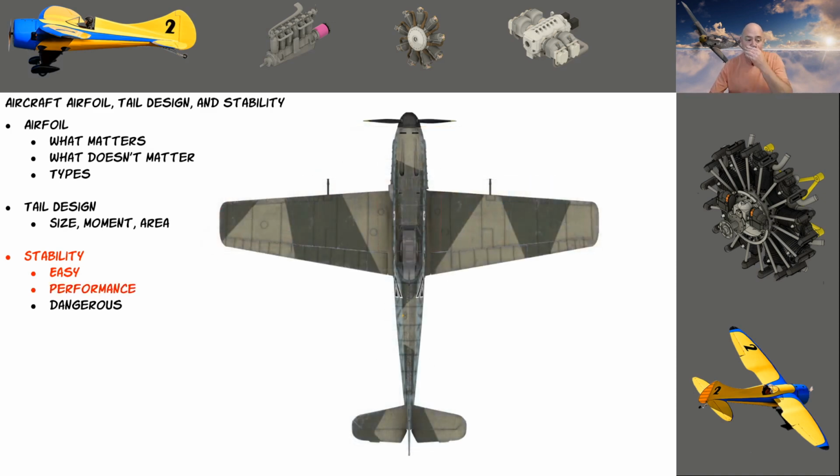So then we start talking about a plane that is easy as far as stability, but it is higher performance. So you might have a fully symmetrical wing. It might be a go-fast plane. And if you don't know this, an airplane can stall at any speed. I don't know how many times I've heard people at the airfield arguing, it's going plenty fast enough, it can't stall. And just so you know this, relatively speaking, most wings will stall at 15 to 16 degrees of angle of attack. That's pretty much a given at the point where the wing quits to fly.